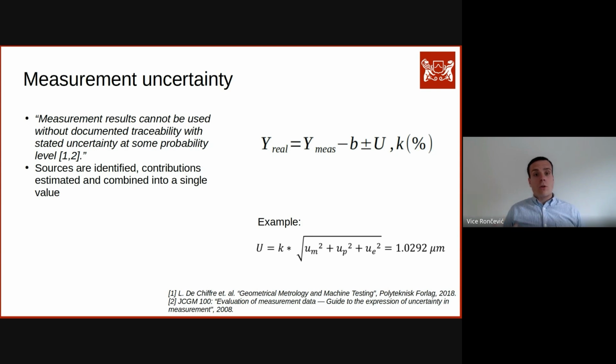And how do you actually compute a measurement uncertainty? Well, there are documented ways and traceable standards and procedures to achieve that. What you essentially do is compute the contribution at each step of your process that contributes to the ultimate uncertainty, and that is first and foremost the effect of, for example, the environment, the temperature, the humidity in the room in which you are measuring your component.